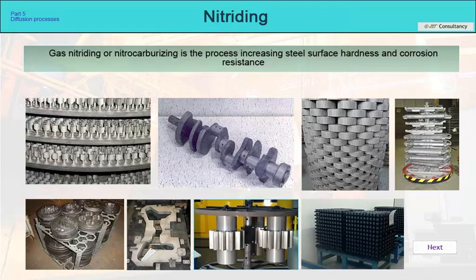and corrosion resistance. Since it takes place at relatively low temperatures, low deformations are also an accompanying phenomenon. The advantage of this process is the high gas penetration between parts, which is why it is advantageously used for batches of small goods, where the positionability of parts can be problematic. It is currently applied to various structural parts, gearbox parts, shafts, or tools. The versatility of this technology is also in the fact that we can nitride both small and oversized parts.